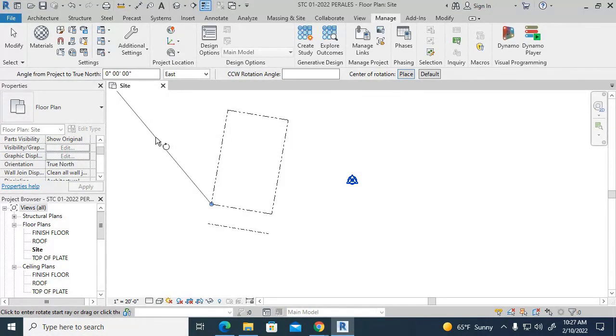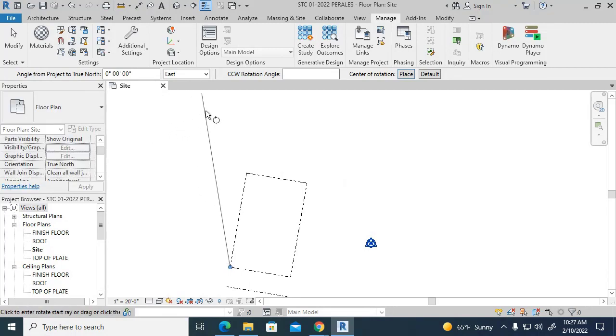The difference is this: it works different than AutoCAD. After you've placed that corner, what you have to do is first click 90 degrees vertically up. This is important. You must follow the steps this way or else it's not going to work. You're going to click vertically up, straight. Click there.